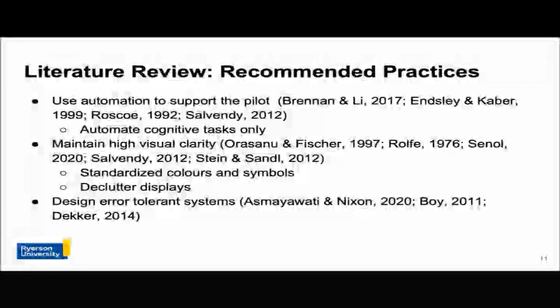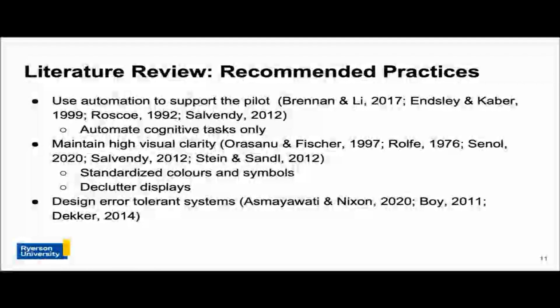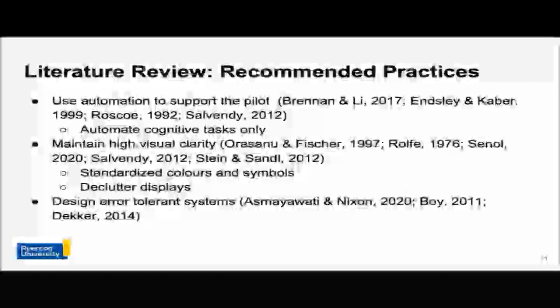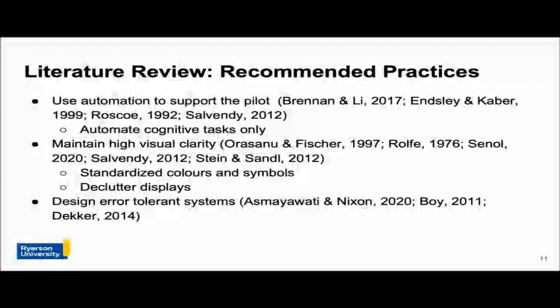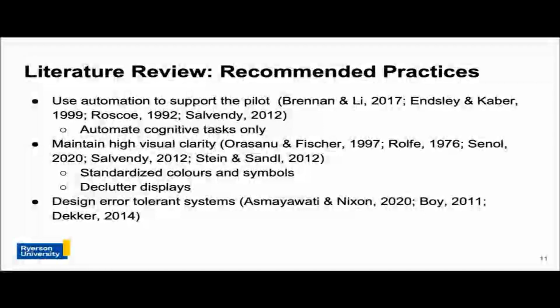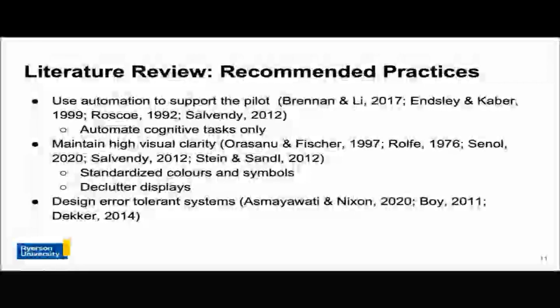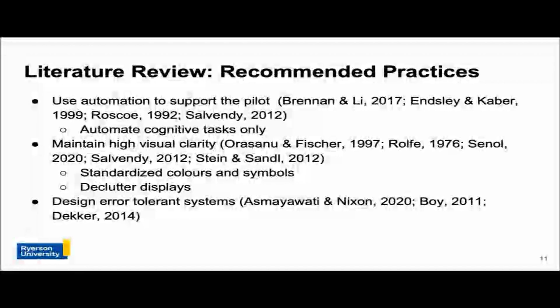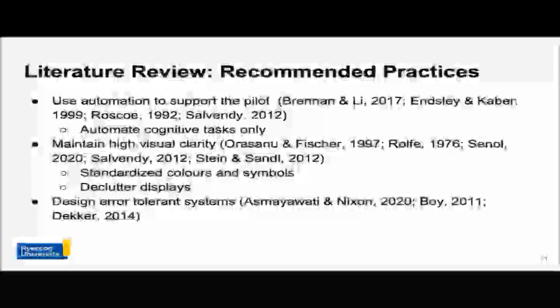Automating cognitive tasks such as memory retrieval provides help to the pilot when in high stress situations. At the same time, it allows the pilot to make decisions based on their past experiences, hence taking advantage of the creative nature of humans. Human factors specialists state that task execution should not be automated. That is, the aircraft should not inherently do things for the pilot. When task execution is automated, the pilot is forced into a monitoring role, which is a task that humans struggle to do. The pilot can then become bored and complacent, which results in low situational awareness and high chances for error to occur.